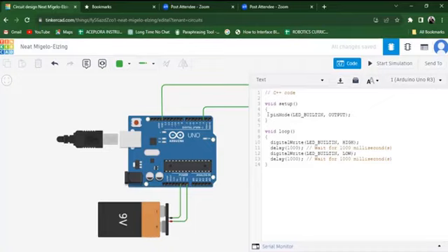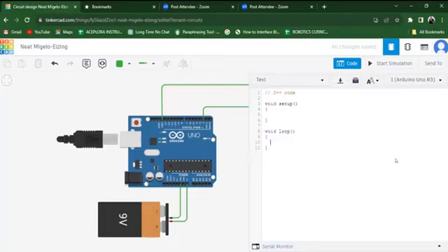Now, I want you to do this. I want you to highlight where you have pin mode and backspace it. Remove it. This is just a default code that has been written. I want us to write it again. What I want you to leave on your screen is void setup, the curly brace below it, and the curly brace next to it. Then the void loop and its two curly braces. This is just what I want you to have on your screen. Have you done that? Okay, good.